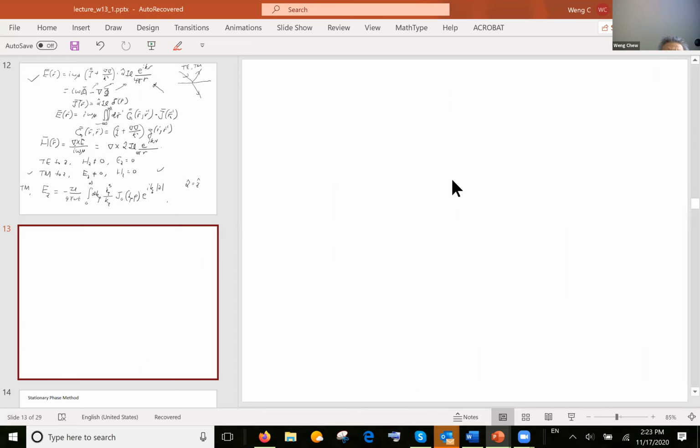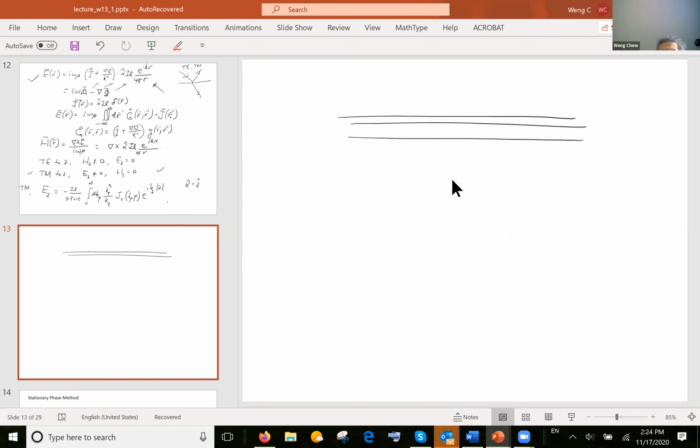We know how to expand the point source field in terms of summations of plane waves. Then if we were to now put it on top of a layered medium, we are very good at layered medium because we have used transmission line theory to solve this many times over. And let's assume that this particular electric dipole is pointing like this, and it's at the height d1 above the interface. And let's assume that we have mu1, epsilon1 in that medium over there.